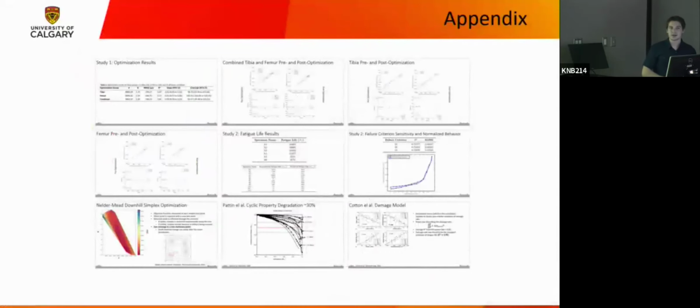So we do this in-house. Now, here's the weird thing about this whole optimization. When we do damage model optimization, we run all those simulations in parallel. So this is all parallel processing. We actually wouldn't benefit from using any type of supercomputer here because our bottleneck, and this is why it might make sense to go back and develop our own FE method, or do a UMAT, to cut down on this pre-processing time, is the time that the software we interface with takes just to analyze the input file.